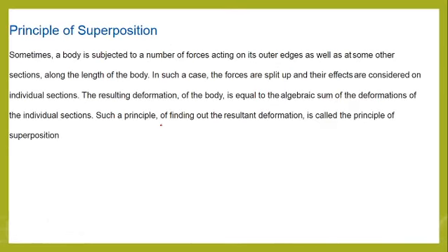Now we go to our new topic, the principle of superposition. Normally a body will be subjected to more than one force, so we have to analyze the forces acting on it. If the body has different areas of cross section, it will be difficult to analyze the whole force in a single stretch. So we will cut the body into small pieces and analyze the total force acting on the body. That is called the method of superposition.